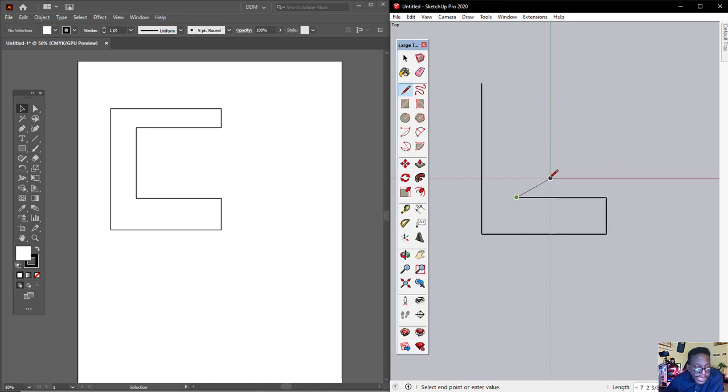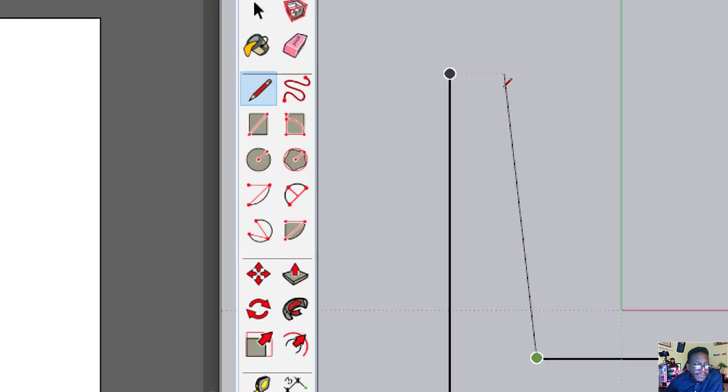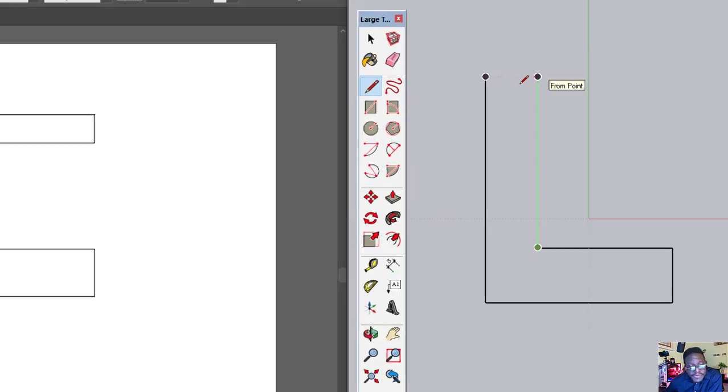Additionally, notice how these snap points might come up when you try to draw. So it's kind of like Illustrator, where it's helping you to be accurate, right? And it also gives you a bit of what you call polar snapping, because you can see these dash lines. If you try to hover at a point, don't click, just hover over it and move, you will see it giving you this dash line that you can use as a kind of reference to know if the line is actually straight. So that is pretty cool.